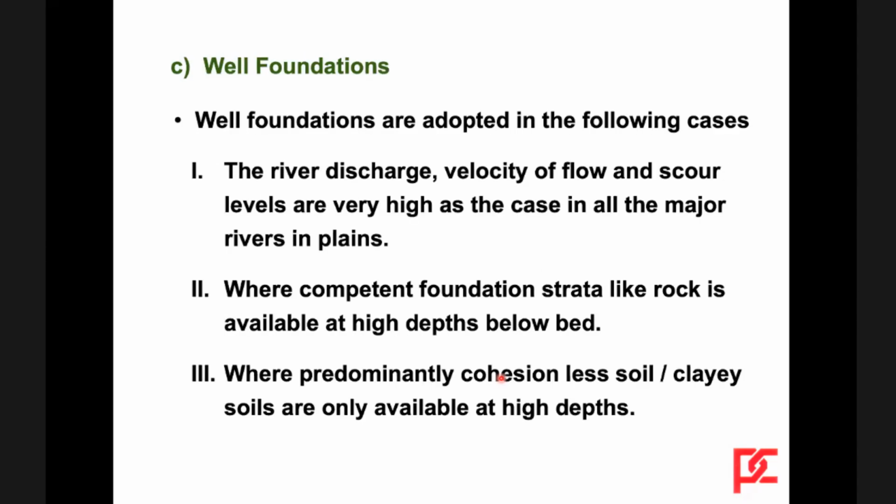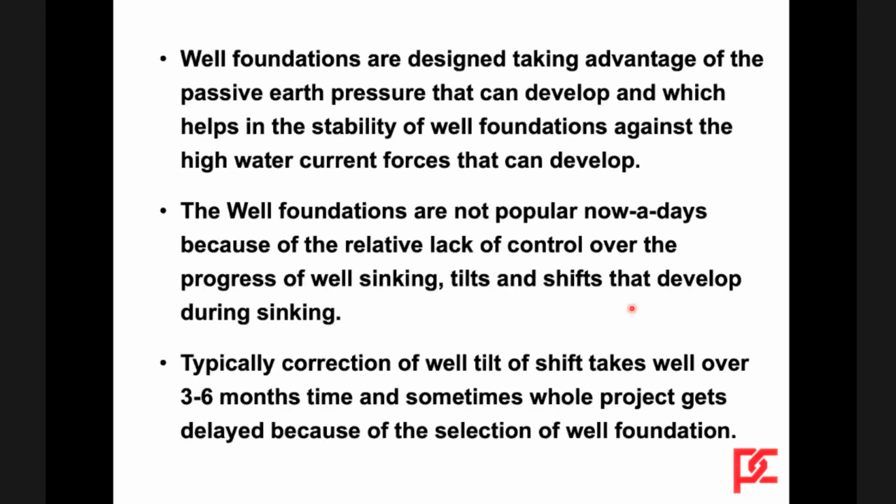Well foundations are adopted in the following cases: the river discharge, velocity of flow, and scour levels are very high, as in the case of all the major rivers and plains, where competent foundation strata like rock is available at high depths below the bed, where predominantly cohesionless soil or clay soils are only available up to very large depths. These are also the places where well foundations are adopted. Well foundations are designed taking advantage of the passive earth pressure that can be developed, which helps in the stability of the well foundation against the high water current forces or seismic and wind forces that can develop.